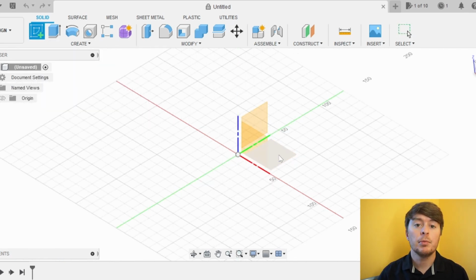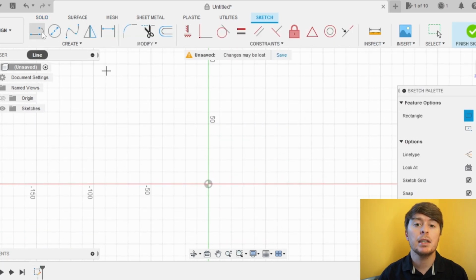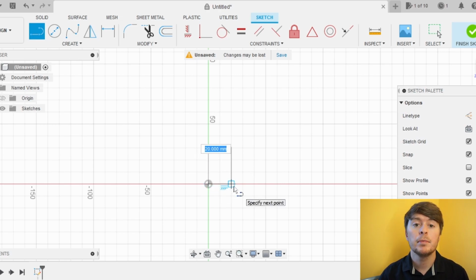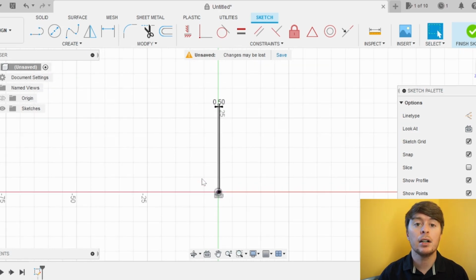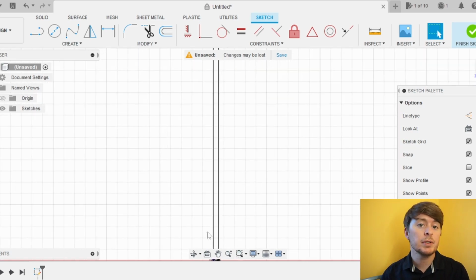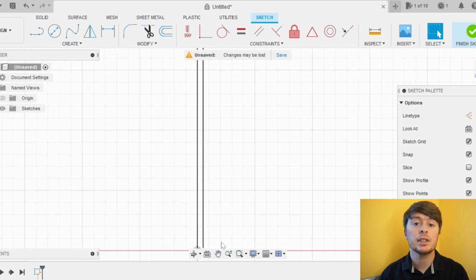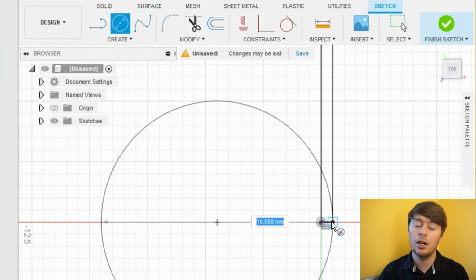Once the software is set up, we're just going to create a very simple curved channel. We're going to do this by making a 500 micron line, so half a millimeter, and then we're going to draw a circle with a diameter of 20 millimeters. This is so that we can get a lovely arc for our curve, to model something you may have seen in my previous video on inertial separation microfluidics: that initial spiral, that initial curve.